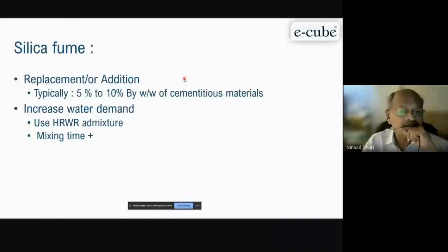For general concrete, high performance concrete or high strength concrete, even if you design M100, more than 10% is not advisable to use, because mixing is difficult. The mix becomes very, very sticky, very difficult to handle. Maybe in the laboratory we can design it, but one has to see how I can make the concrete in the field. So accordingly we have to fix the dosage of the materials.